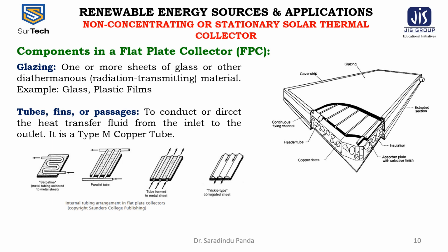The commercially available grades of window and greenhouse glass have normal incidence transmissions of about 0.87 and 0.85 respectively. For direct radiation, the transmittance varies considerably with the angle of incidence. Anti-reflective coatings and surface textures can also improve the transmission significantly. The effect of dirt and dust on the collector glazing may be quite small, and the cleansing effect of an occasional rainfall is usually adequate to maintain the transmittance within 2 to 4% of its maximum value.